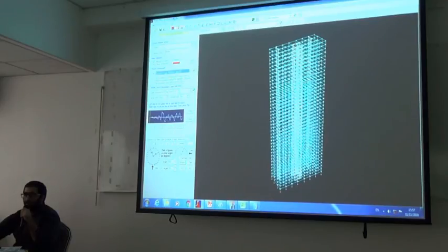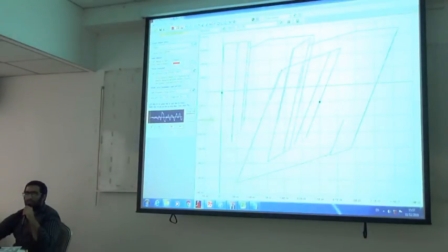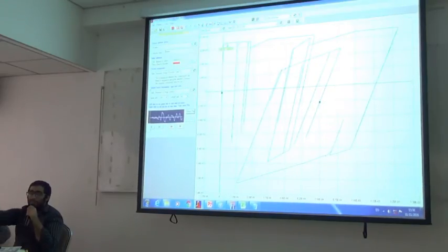Okay, so you can see some hysteretic loops being plotted over here for the girder. But these do not look smooth because the force itself is not that smooth continuously. It's not a controlled force. And in this one, the y-axis is the moment value. The point where I have stopped, the moment value is 682.9 kilonewton meter, right? And the rotation number is 2.5 times 10 to the power minus 5, very, very low rotation.